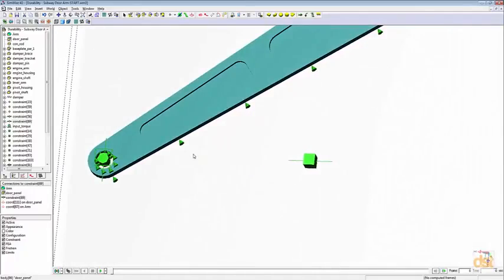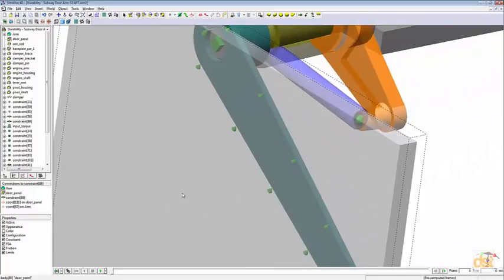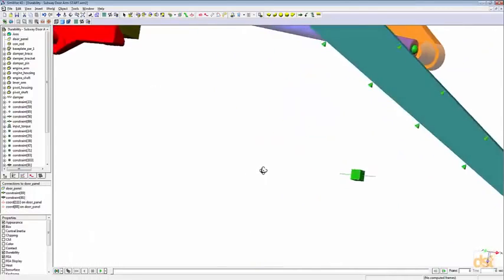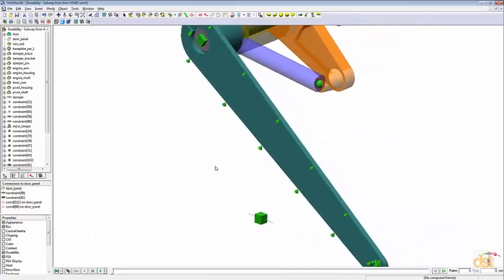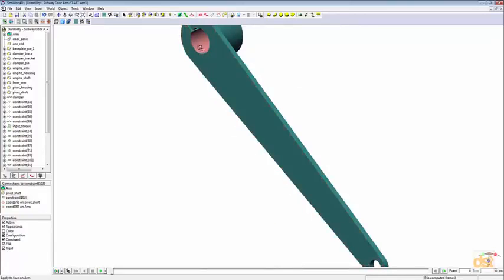Notice how we have another graphic that's still showing out here. That graphic belongs to the other constraint that's connected on this end. Let's go ahead and hide the door for simplicity here, and we can see this graphic right here. Notice when we hover over the graphic, the constraint that's associated with the graphic will highlight. So if we hover over the graphic here, notice the fixed joint at the upper end of the arm. Go ahead and right click on it, choose Distribute on Face, just like we did for the first one. Select the inside diameter.